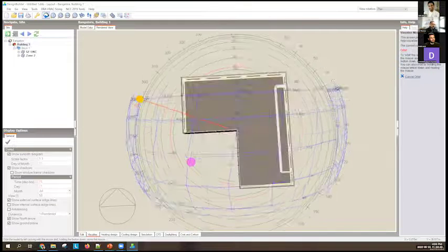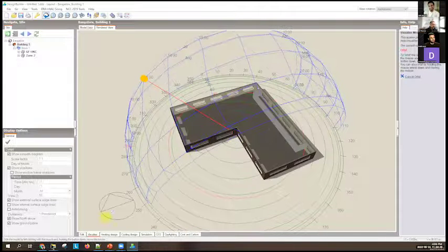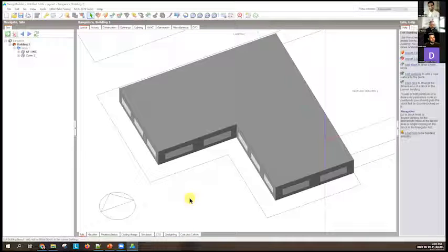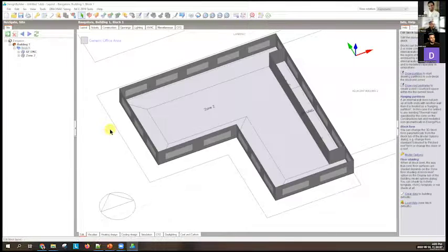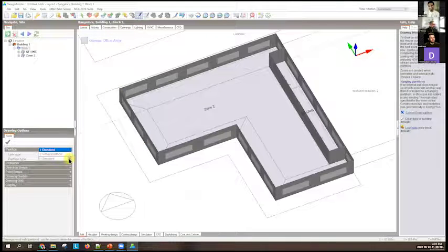Okay, that's why this whole exercise of trying to explain it to you. So back to where we were. I am dealing with a conditioned building today. So here's my block. And what I'm going to do is break up some more of these zones into perimeter zones. To do that, I take my partition tool, but instead of a standard partition, I use some virtual partitions.